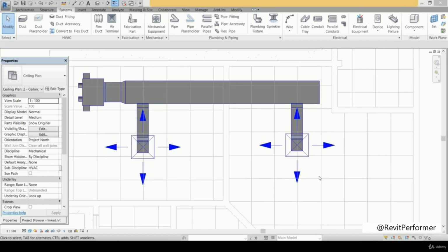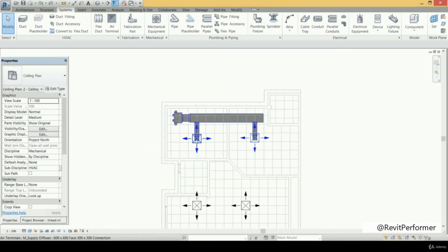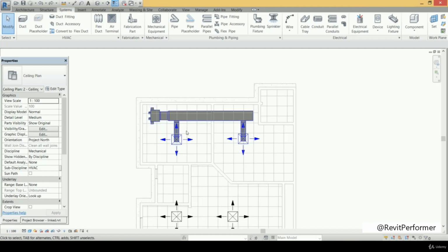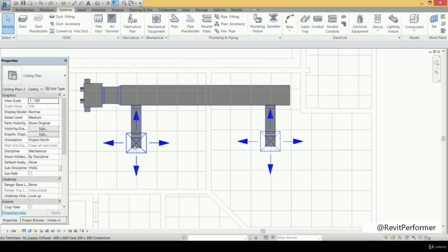Now you may note that when we created the duct, it was created with the default properties, on the default offset, for example, or on the default dimensions. But in some cases, we need to set the duct on a specific level and also to have a specific width or generally some specific dimensions, as we may need to make an array of branched ducts, for example. So suppose that instead of 2 air terminals, we have 5 air terminals in that direction, and each of them will be fed by the same branch. That means that branch will have the same offset as the forward branches, and they will also have the same dimensions, as those air terminals may have the same airflow through them.